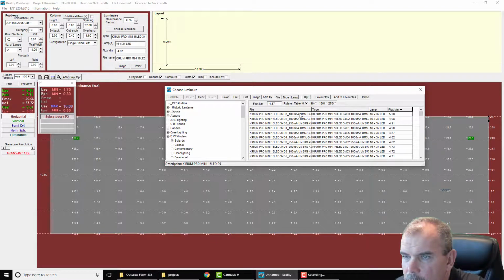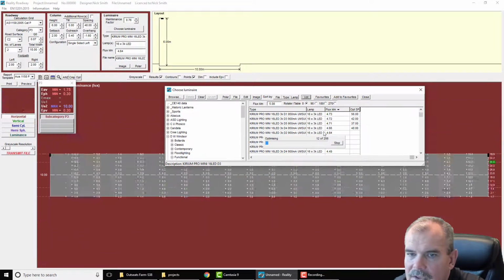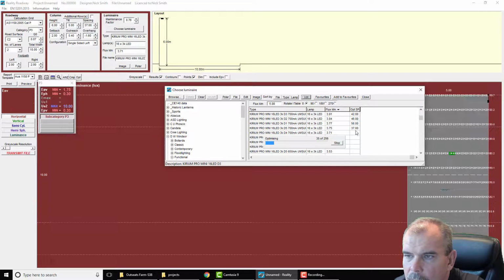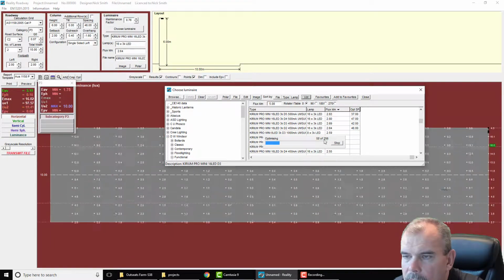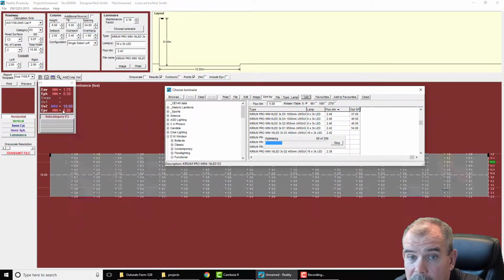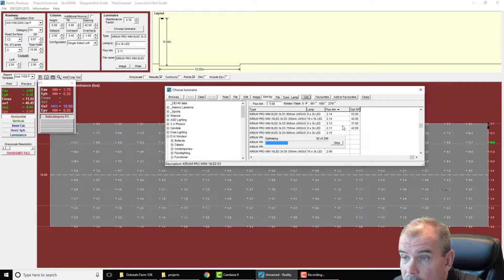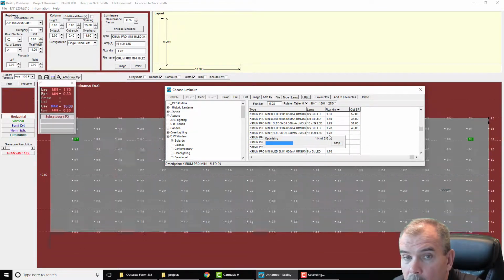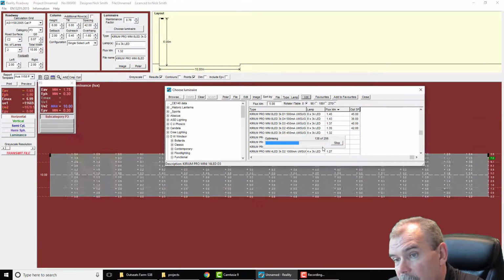The alternative is that we click on the file and select this opt button at the top of the luminaire dialog box. What that will then do is go through each of the optics that are available to us, and calculate for every single one the maximum spacing that can be achieved, based on the road configuration and the target levels that we've included. In this case we've excluded the EPV. For each of those it will calculate a solution that will work, and sooner or later it will get through all of those.